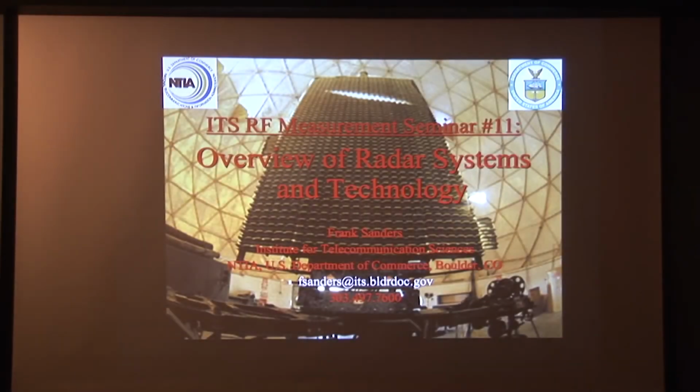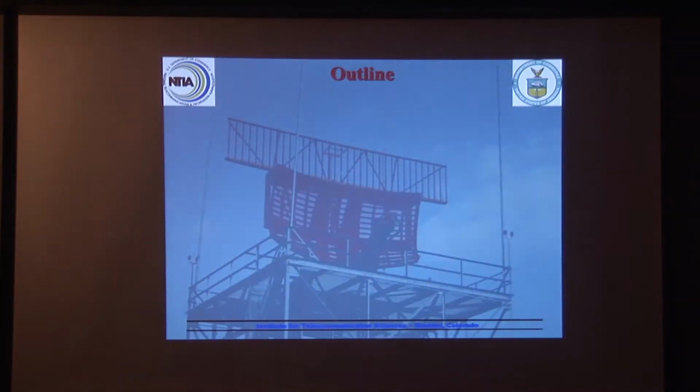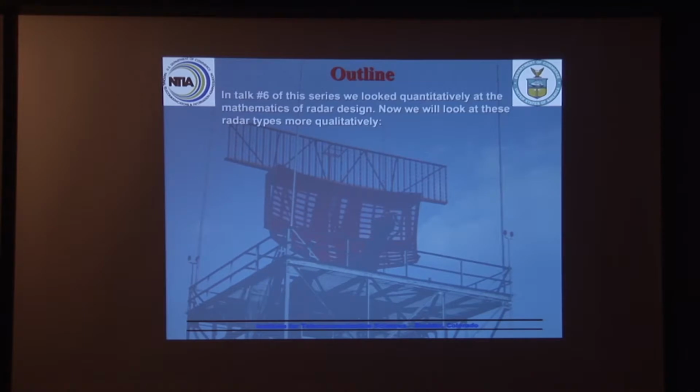This is ITS RF Measurement Seminar number 11. Today's talk is Overview of Radar Systems and Technology. This title slide, by the way, shows an advanced radar type called a TPS-59, which is a radar that is carried with an antenna on a trailer, and it rotates mechanically, and while it's rotating mechanically, it scans a beam electronically in elevation. So, here's what we're going to be going through.